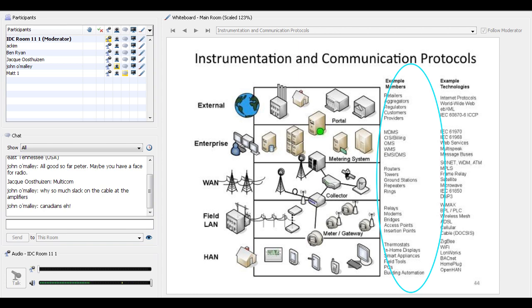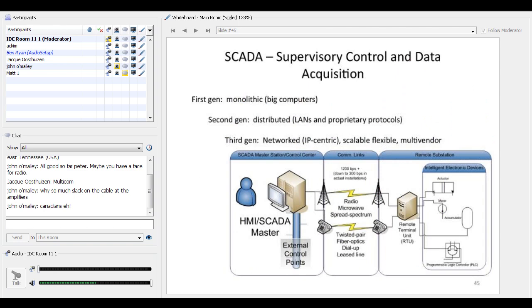Then on the right-hand side, there are the protocols. I keep hammering this, guys, because you've got some great courseware here, these modules that say this is using DNP3, this is using IEC 61850. This particular vendor is using HART. This vendor is talking ISA 100. That one's talking Profibus. This is an instrument that wants a video camera. The video camera is going to require 3 megabits per second, so I have to have a certain type of network that can deploy that. And that is instrumentation circa 2011. It's all in the courseware. I really think you're going to like it.